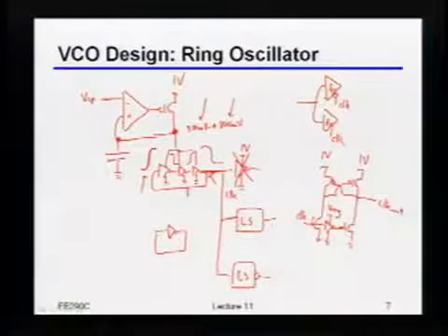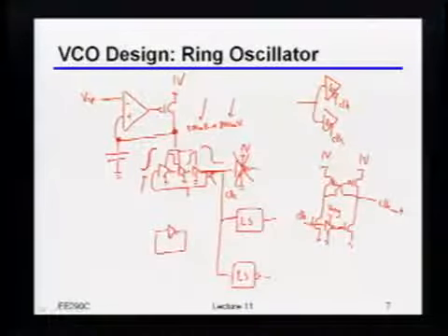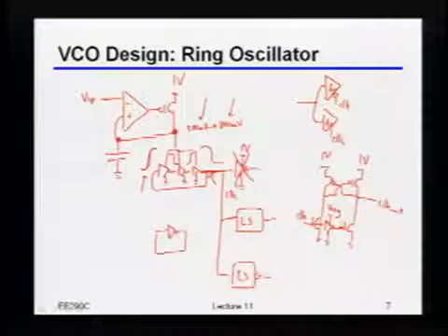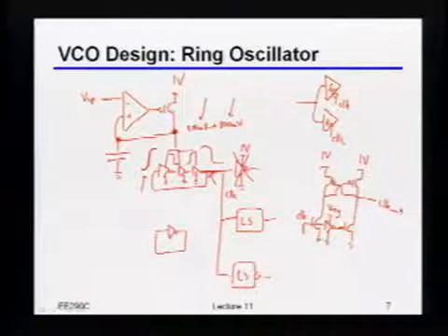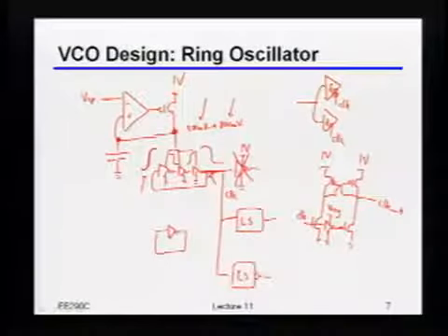Or I guess what you were saying earlier was that you have one clock, like one of the level shifters produces clock and the other one produces clock bar. That's right. So if I just flip which one I called clock and which one I called clock bar here, then that would do that, right? But then you're distributing two different clocks to the serial link. Well, one clock goes to here, and the other clock goes to there. Yes, that's right. Isn't it just better to just split one clock and...